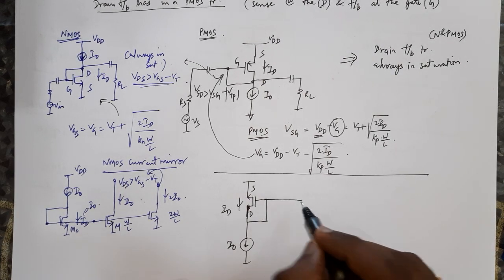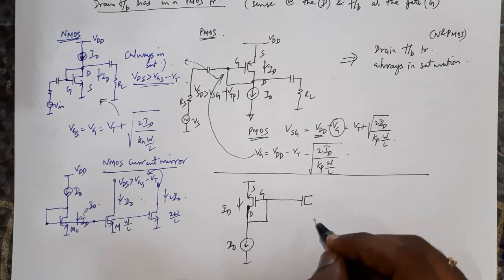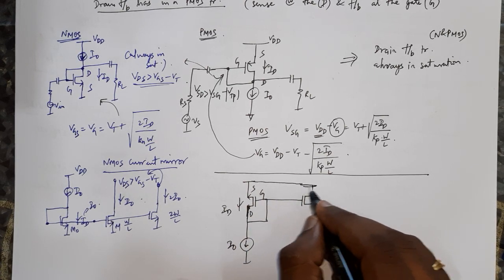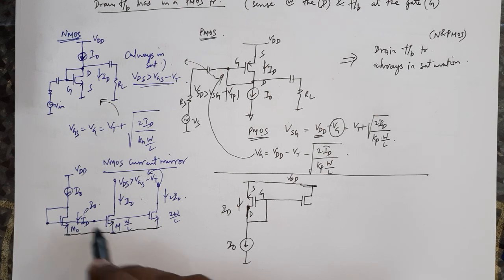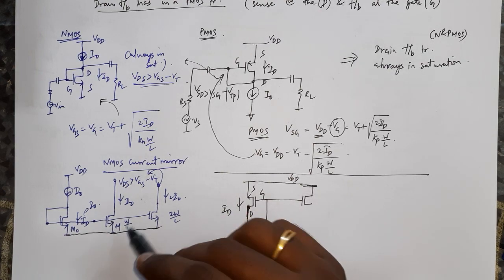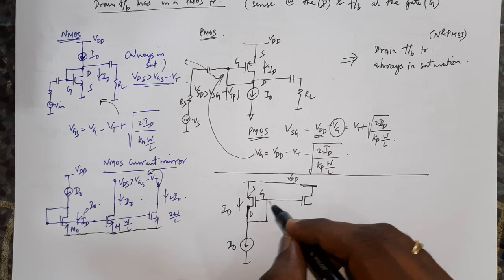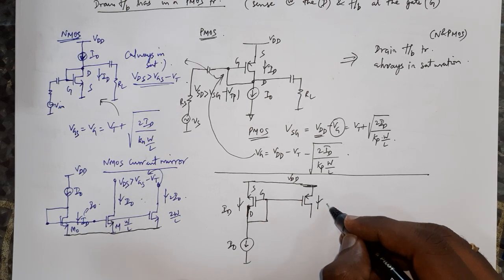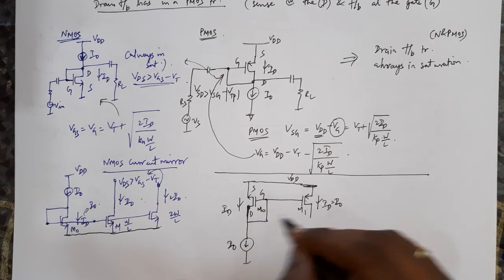Now if I extend this particular gate voltage, this is the gate, and then bias it to this transistor, and as long as this source is also equal to this voltage, which is at say VDD. Similarly here all the sources should be grounded, then only their VGS will be the same. VGS is to be the same for all these transistors, it's a mandatory criterion, then only the current will be the same if you keep the transistor drain voltage so that it is operating in saturation. So here also VG is the same, so maintain VS also the same. In that case I'll have this current ID equal to I0 if these two transistors are identical. M1 and M0 will have the same W by L and so on.